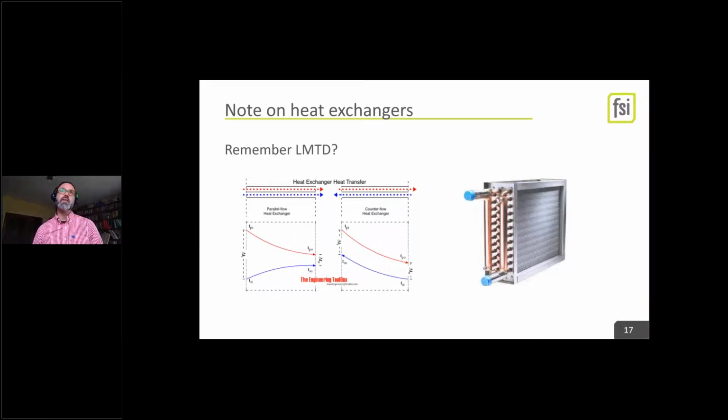So if we don't have original design drawings or even better submittals that tell us what that coil was, what was expected, it's difficult to say this coil designed for 180 degrees on this worst case day is going to work fine with 160 degree water, or is going to work fine with 140 degree water.